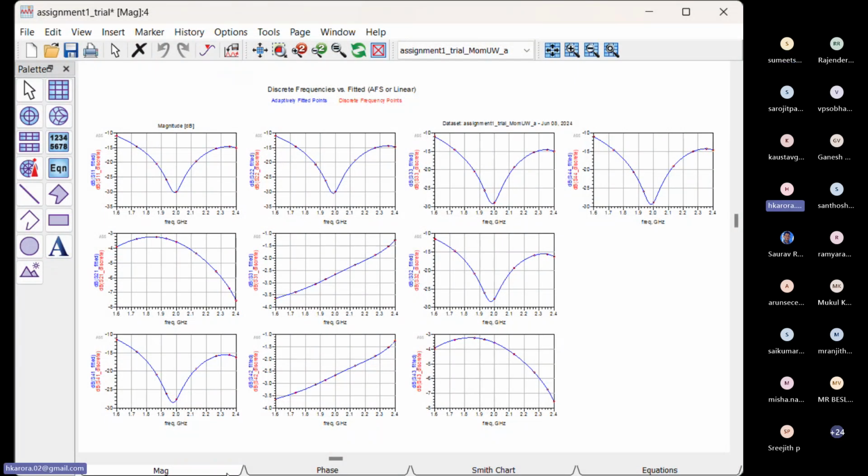I've basically created the schematic and then proceeded to layout. And then after that I did EM simulation, and these are the results I got. These are the EM simulation, but you should go to co-simulation also. Anyway, it will be similar here because you don't have any lumped components, I suppose. So then what is the problem?